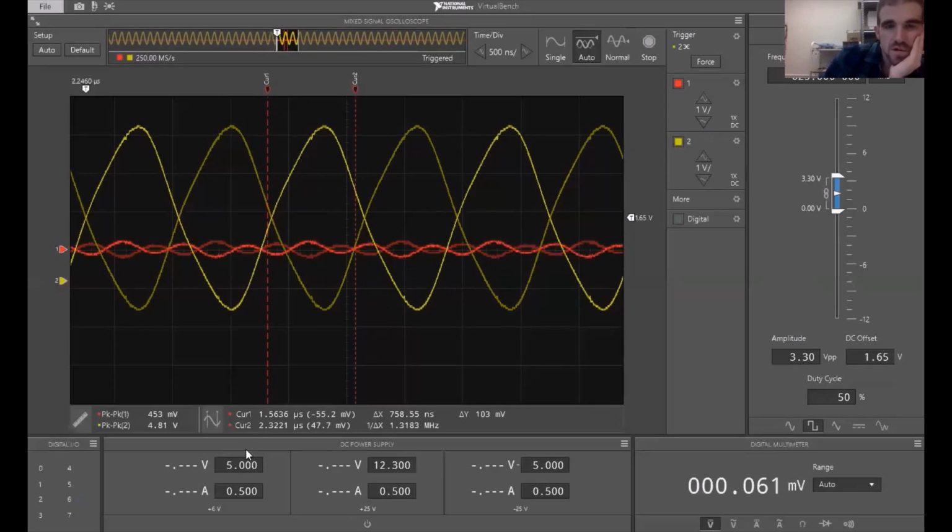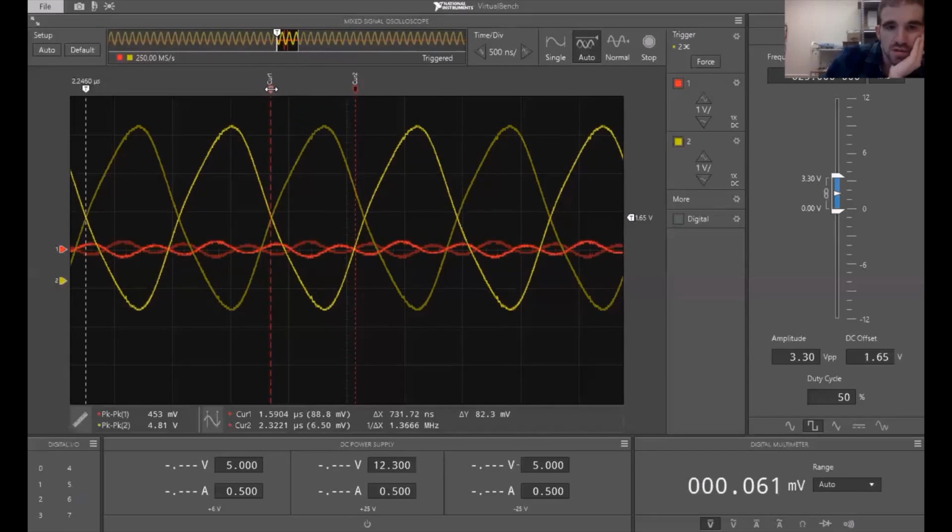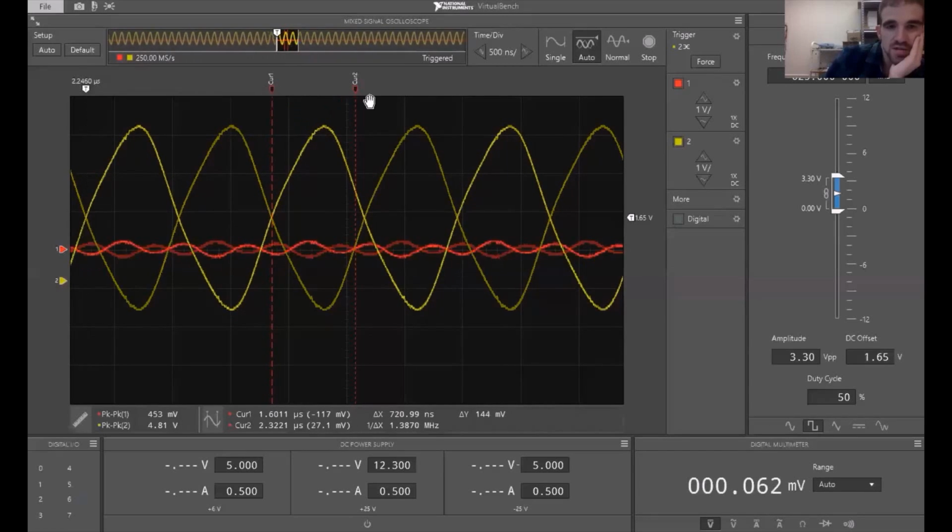So for the width of the one, should get the same thing. But now for the width of the other, click stop, and I measure these 2 points. The eye width is approximately 323.94 nanoseconds. And one can also notice as you go further and further down the line, the number of harmonics actually increases.